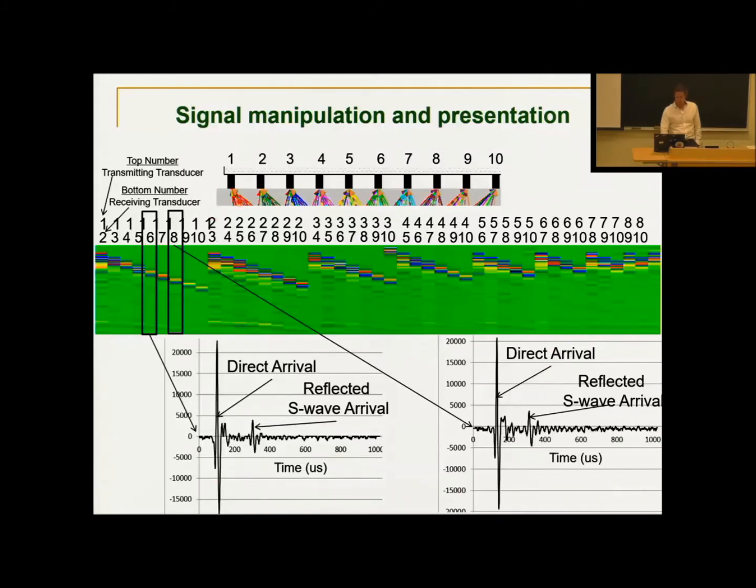So we get some wave components that travel along the surface, but we also get, from that clean shear wave field that I pointed out, a wave that travels inside and reflects back, and that's the reflected shear wave. This is the concept of the pulse echo shear wave: send and receive, look for a reflection from a defect. We're interested in that component.